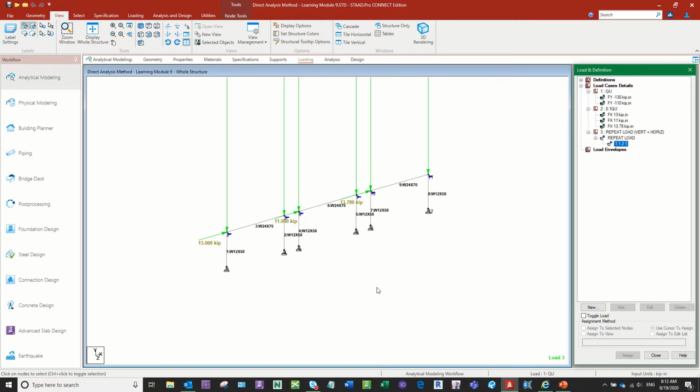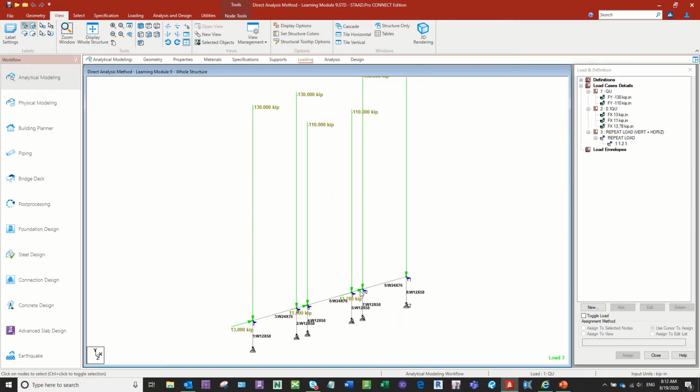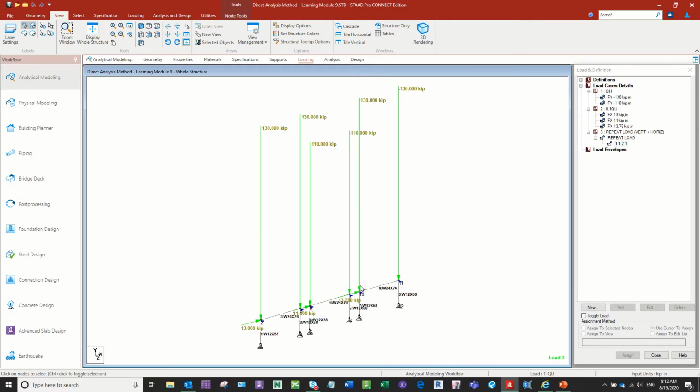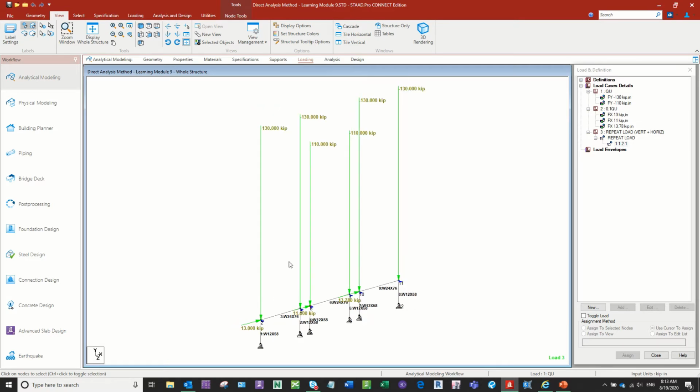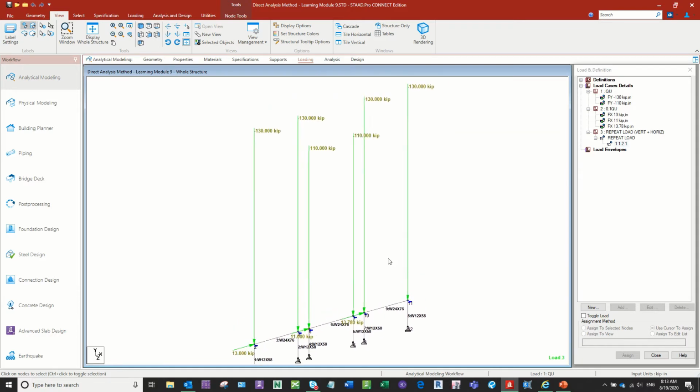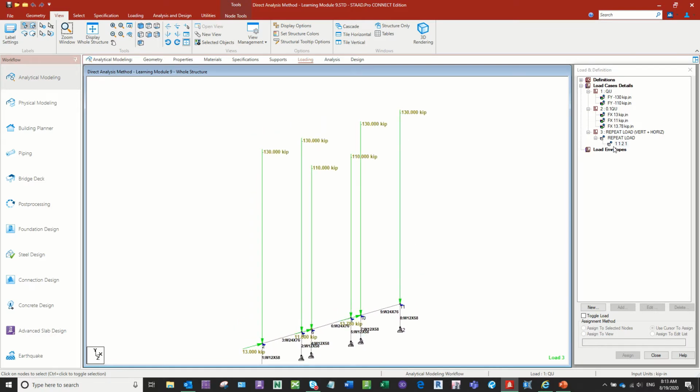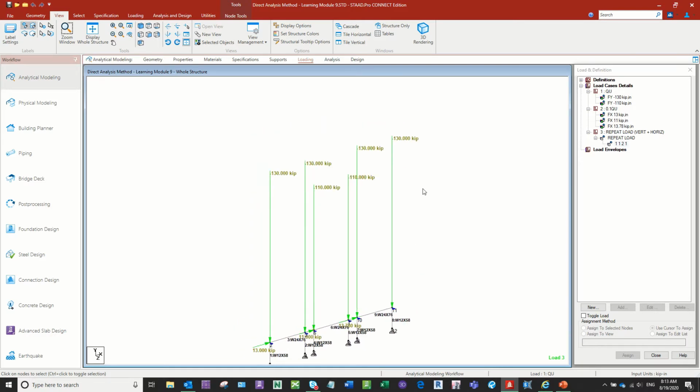And so this load case would show that you have both vertical and lateral together. All right, shown here again, it's all scaled up to show you the magnitudes of the force that's acting on the structure. That's why you see these vertical loads so much higher than what's represented for the lateral loads. And that's how we essentially get the analysis to run.